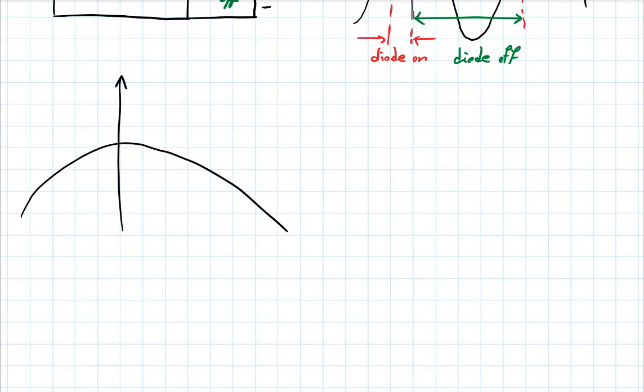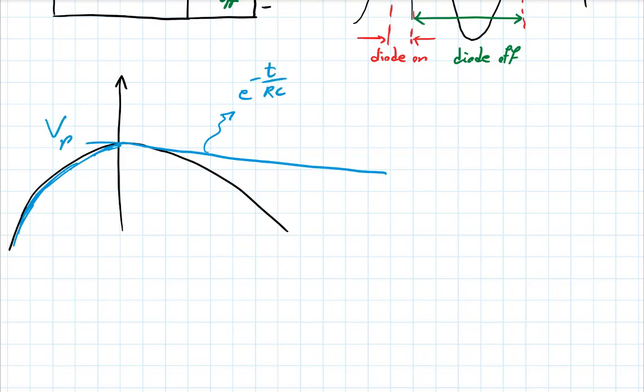so this is where we have that peak of that input voltage. And then I have the output voltage going up with the input. And now that the input is going down, I see that the output is going to start a decay, an exponential RC type decay into the resistor. So is this how things happen? And is this curve really exponential of minus t over RC, let's say with a peak value VP? Or do I need to think a little more if I want it to be really accurate? Is there something there to think about?